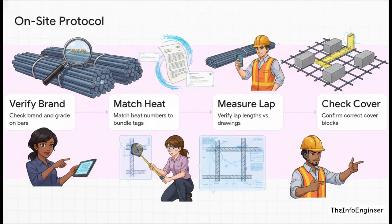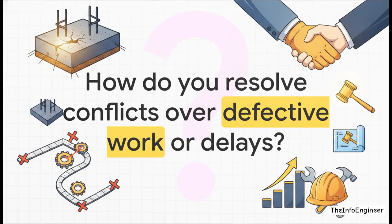So let's walk through a strict 4-step verification protocol you can virtually hand to the recruiter. 1. Physically verify the brand embossed right on the steel bars. 2. Demand the test certificates and match those heat numbers straight to the bundle tags. 3. Pull out a tape measure and physically verify those lap lengths against the drawings. And 4. Confirm your cover blocks are perfectly placed. Executing these steps catches substandard materials dead in their tracks, stopping brittle collapses before a single drop of concrete is ever poured.